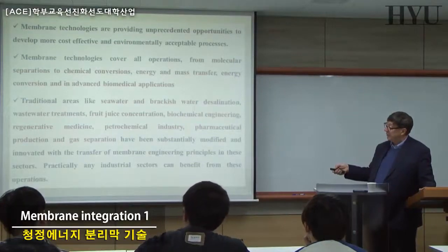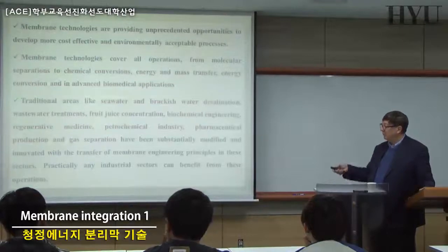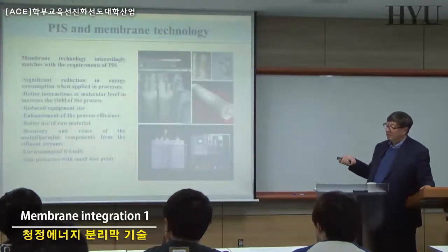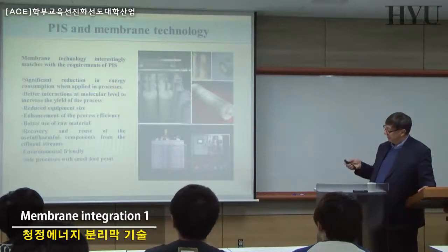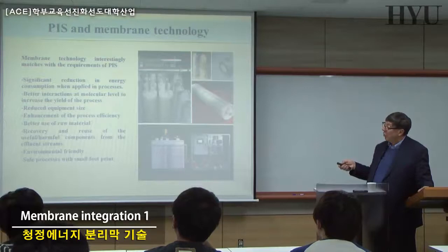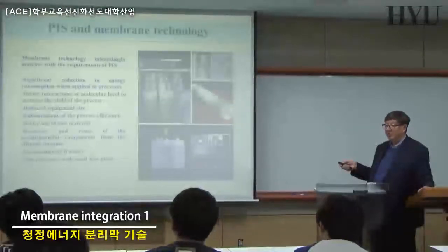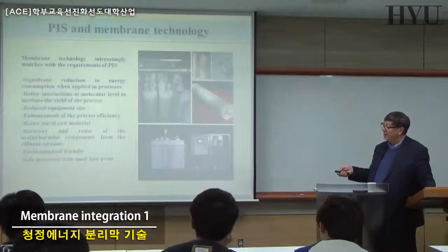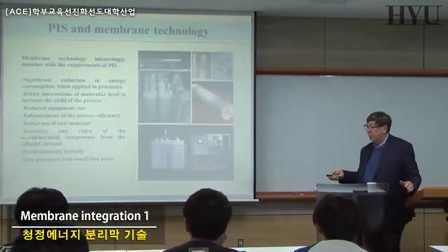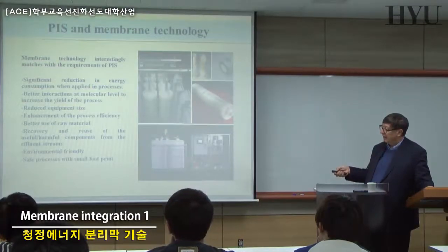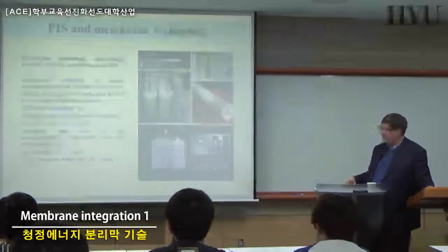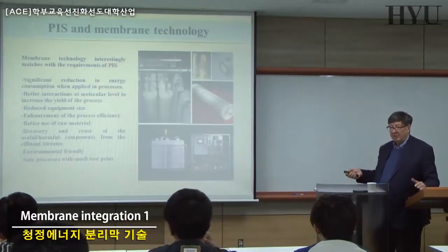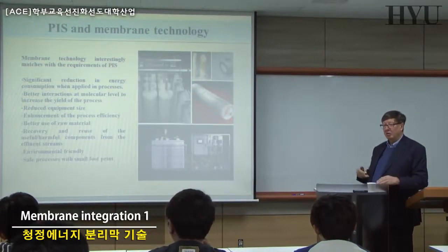And more and more in the petrochemical industry, pharmaceutical production, etc., the principles of membrane engineering are becoming quite significant. These systems are already present at the industrial level, as I was mentioning, and they are all quite consistent with the principle of process intensification. That is our goal in terms of footprint, efficiency, and optimization in consumption of raw materials, recovery and reuse, environmental effect, etc. Remote control: all membrane operations can very easily be automated. And there's no way you make an MSF, etc., totally automatic.